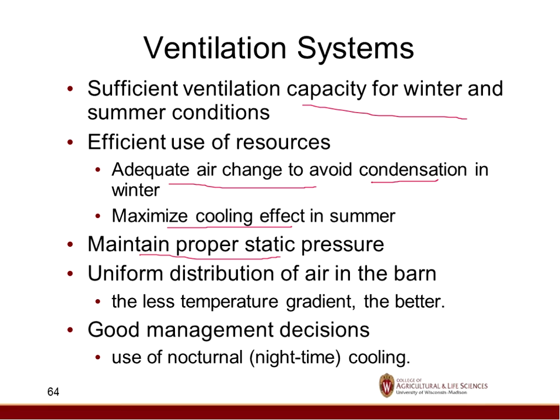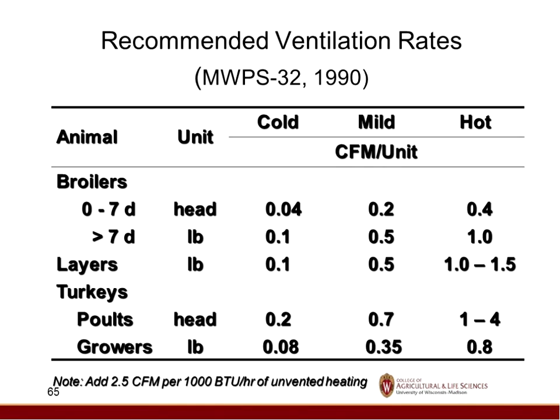Maintain the proper static pressure. That's usually what we can measure to make sure we have uniform or the proper velocity of airflow and distribution of air through the building. And the other, from a decision standpoint, is making sure we're making good management decisions on that. So in summertime, it may get cool at 9 o'clock at night. So, if you looked at the temperature setting, it may shut the fan off, but those animals may still be stressed from being overheated during the day, so we may want to continue doing some cooling at night to pre-cool them for the heat of the next day, essentially.